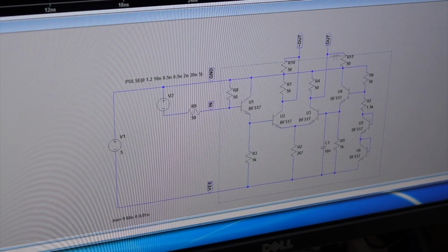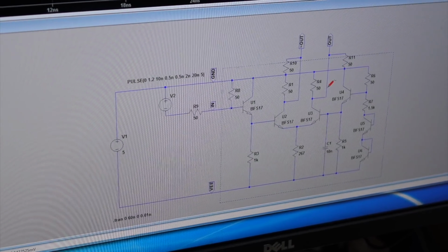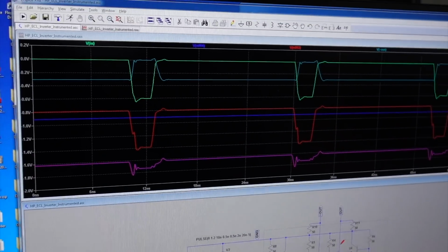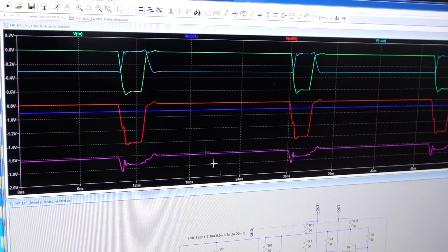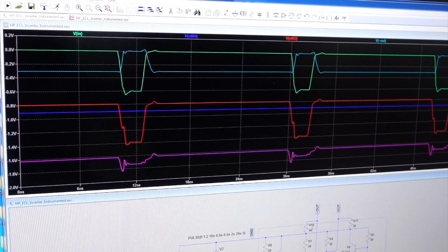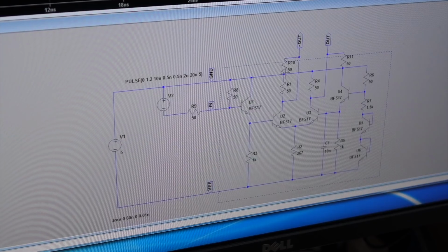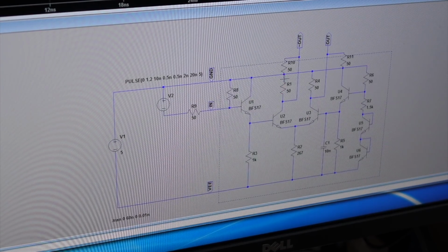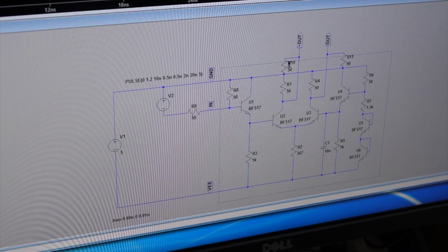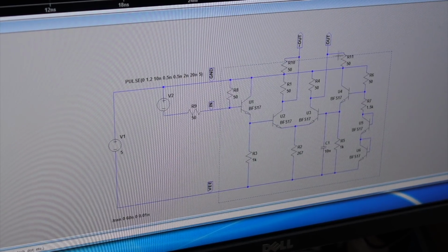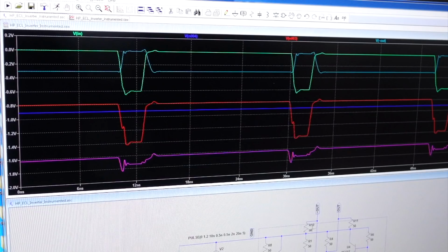So I've added my termination resistors here, and then of course I get half the voltage, right? So I get something that looks like my 300 millivolt. So what just happened is another classic RF design boo-boo. I am measuring the voltage across a 50 ohm collector resistor using a scope with a matched 50 ohm impedance. So I'm basically loaded with 25 ohms when testing and getting half the voltage out.